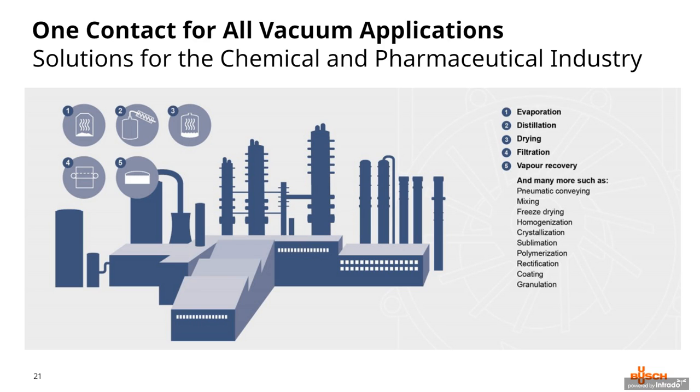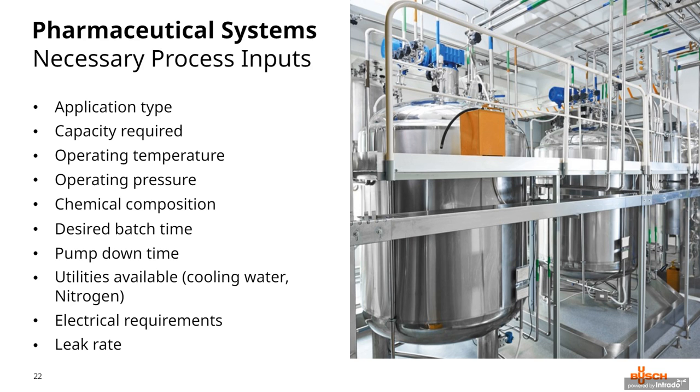Here, the dry screw pump is often useful with these chemicals, particularly when they have low boiling points or relatively low pressures. Lab systems are also common, and typically with lab systems you're going to be using a central vacuum system. With any central vacuum system, you might have a combination and a variation of chemicals being pumped. Therefore, dry screw pumps are often used because they're generally a little bit more versatile compatibility-wise.